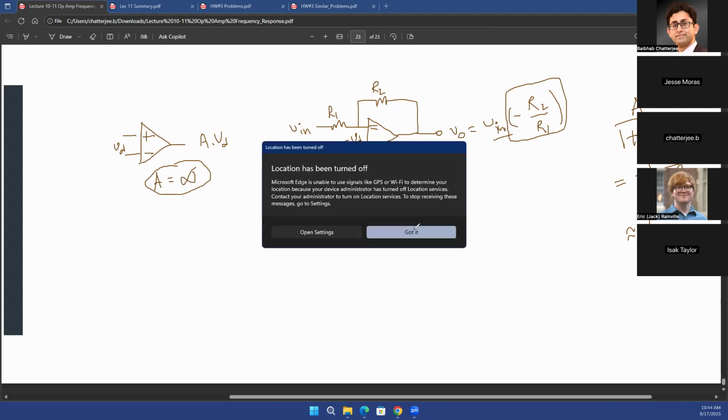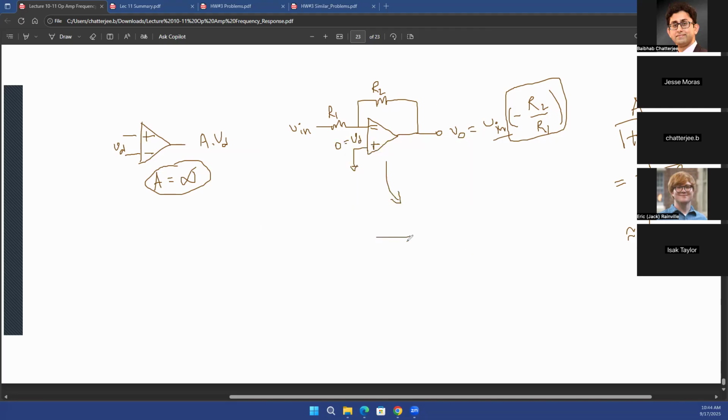That's why I wanted to mention this here. If you draw the ideal op-amp circuit, you have an open circuit at the input side. At the output side, you have this dependent voltage source. Because this is an ideal op-amp, the series resistance connected with this dependent voltage source will be equal to 0, and that's going to be your output VO. Now, part of this is getting fed back using this R2 resistance, and then you have a resistance R1 connected to Vin. Now, because we are looking at the Thevenin equivalent resistances, your independent voltage source at the input can be grounded.